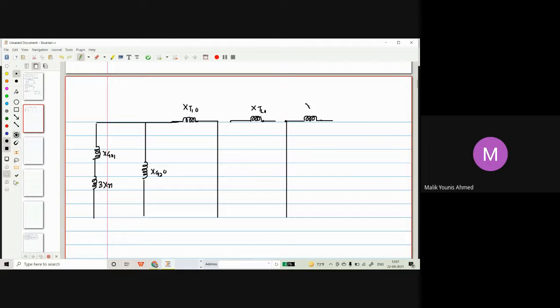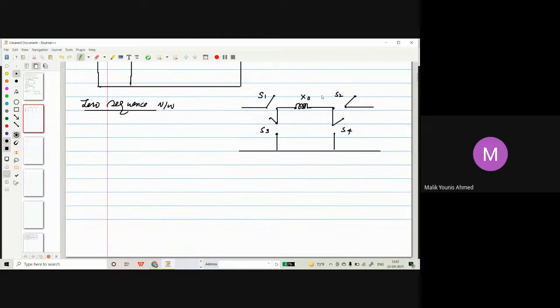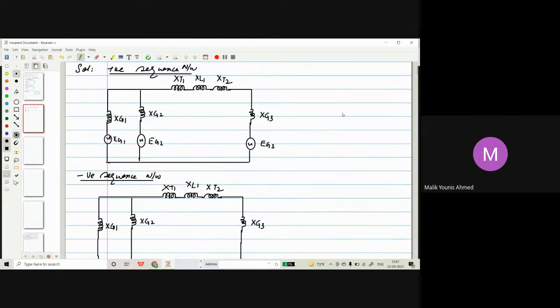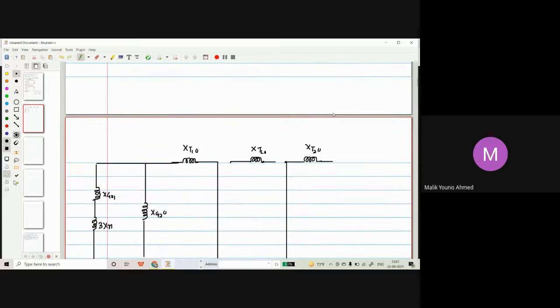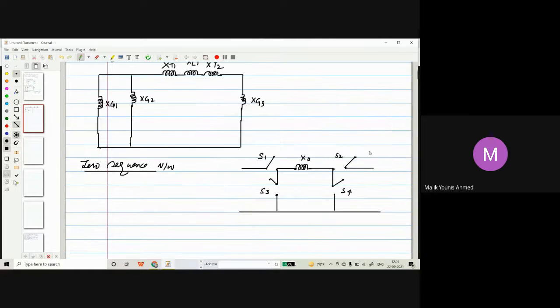That is XT20. Fine. Now coming to the secondary side of this. The winding on the secondary side is star connected, neutral grounded. That means the series switch will be closed and the shunt switch will be open. So we'll close the series switch. This switch we will close. The shunt switch we will not draw. That's all, we have finished the transformers.